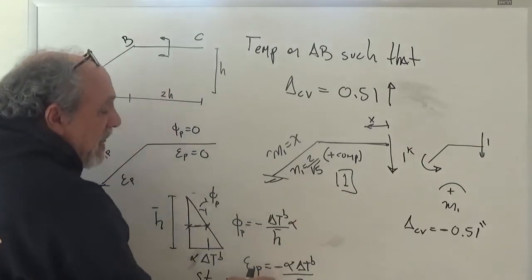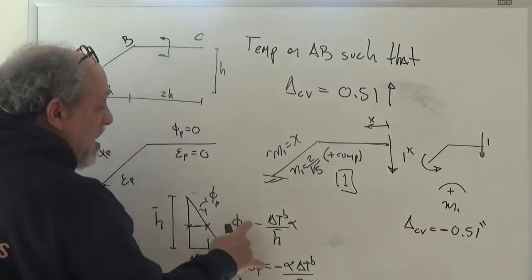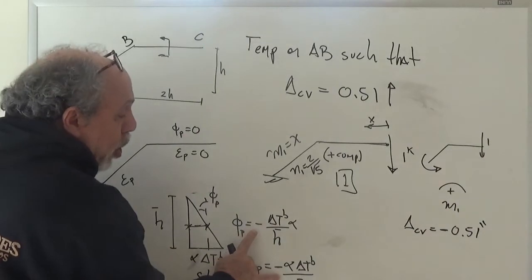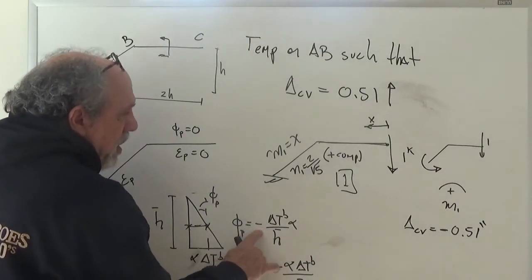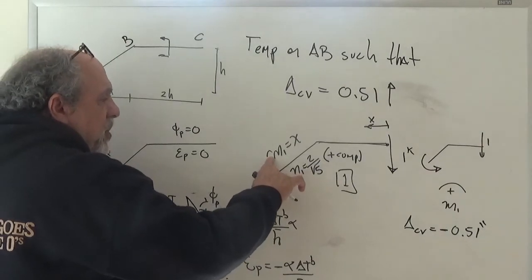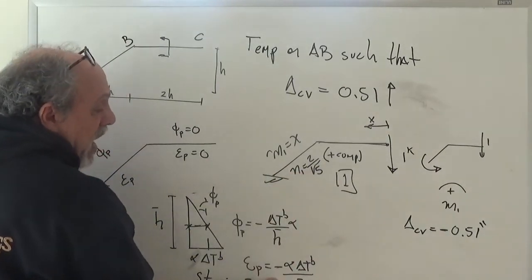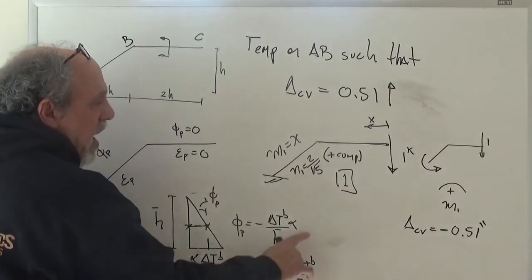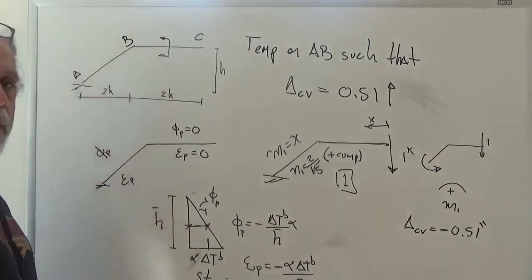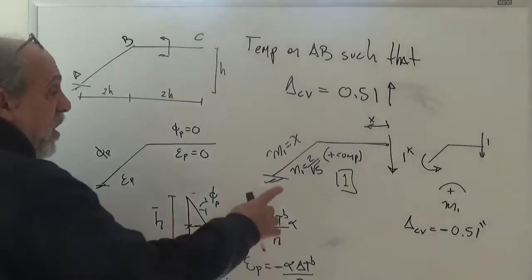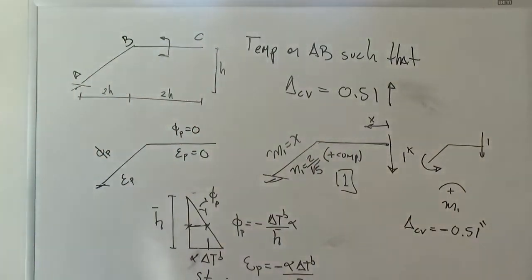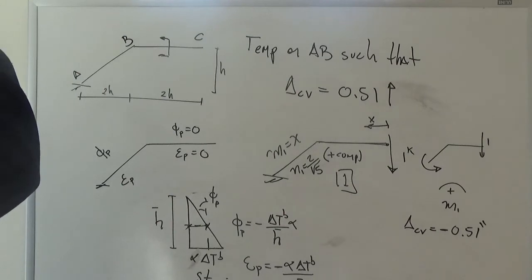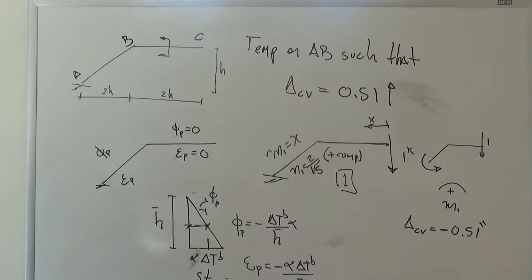They don't really mean that they are always negative or that they're negative because this or that. All these negatives say is that curvature is opposite to the way that moment produces curvature. That strain is opposite to the way that axial force produces strain. That's all it's saying. If we reverse the sign convention here, this would be plus. Now that we have those two things, then it's over, right? We just plug it in.